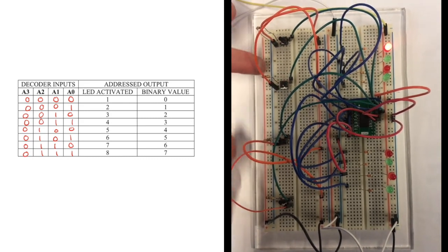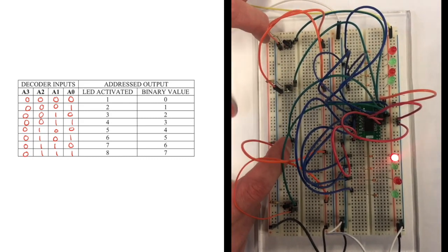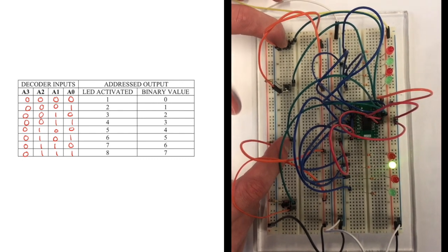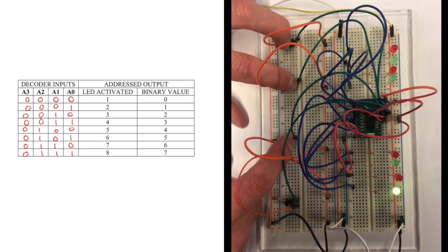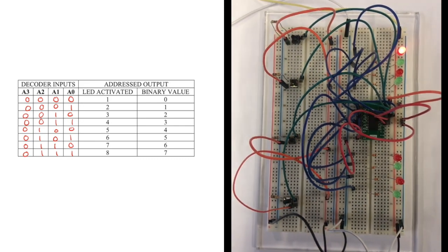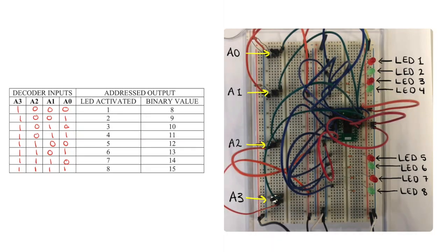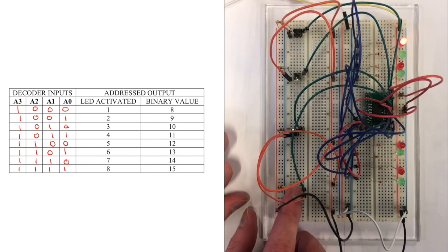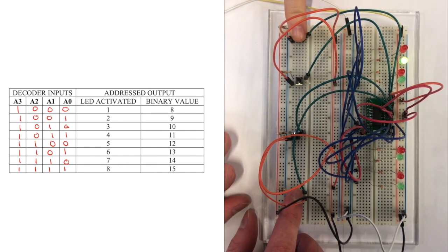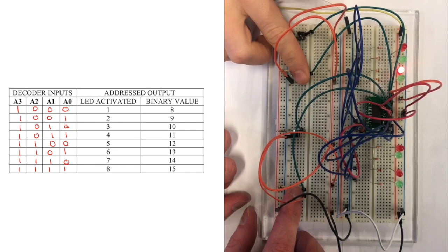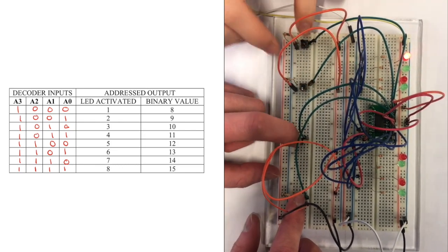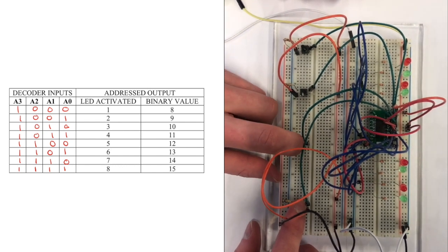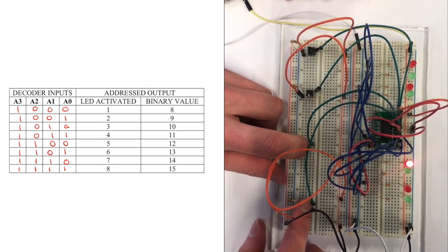We had 4 buttons as inputs and 8 LEDs to show which input led to its output. We connected the LEDs to the first 8 outputs, 1 to 8, to fill out the first truth table. Then we switched the LEDs to outputs 9 to 16 and filled out the second truth table. The truth tables that we used had first binary values 0 to 7 and then 8 till 15, where each binary value has a different combination of inputs.